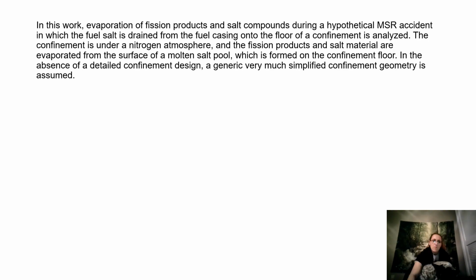In this work, evaporation of fission products in salt compounds during a hypothetical MSR accident in which the fuel salt is drained from the fuel casing onto the floor of a confinement is analyzed. The confinement is under a nitrogen atmosphere, and the fission products and salt material are evaporated from the surface of a molten salt pool, which is formed on the confinement floor.